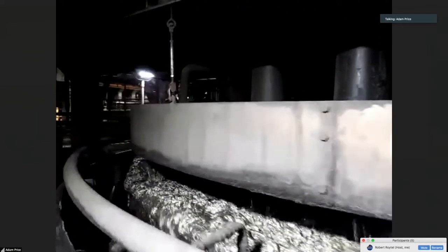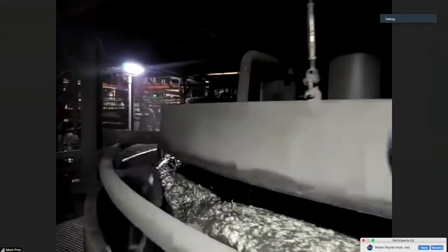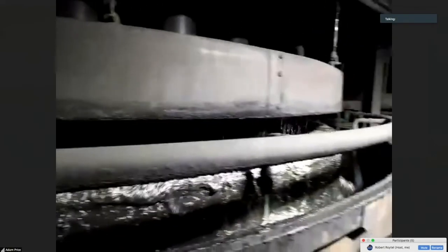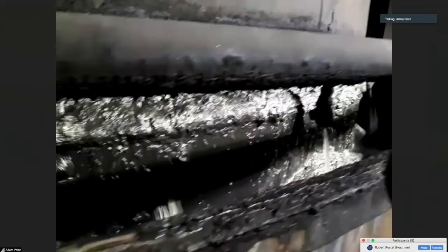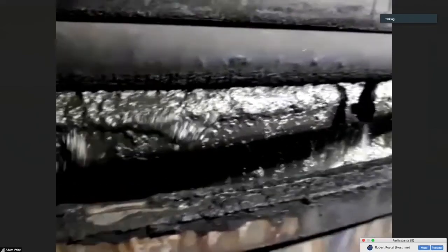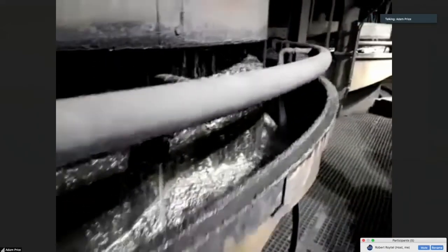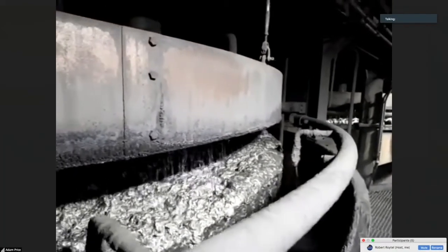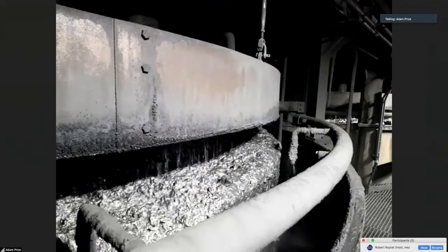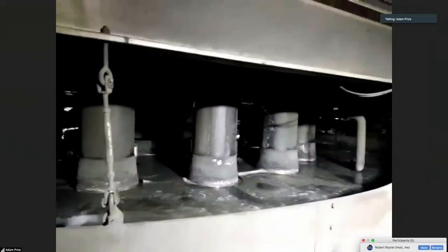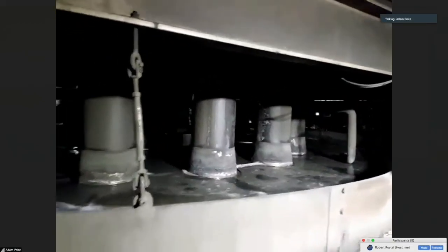As I mentioned earlier, our final concentrate stream is coming from the first 2 Jameson cells, the scalper and the cleaner Jameson cell. The froth washing system makes sure there's minimal entrainment or gangue entrainment in our final concentrate. We're currently targeting 26% copper grade. We manage to achieve that by achieving 28% concentrate grade on the scalper and 20% concentrate grade on the cleaner.